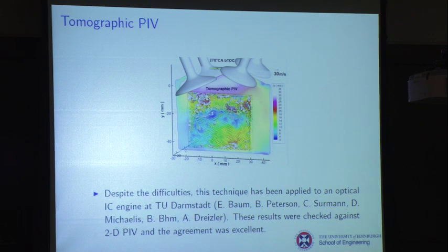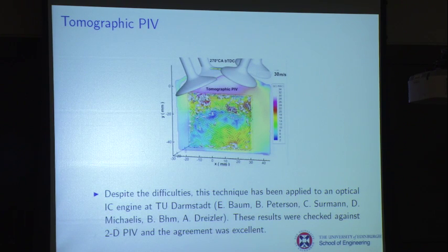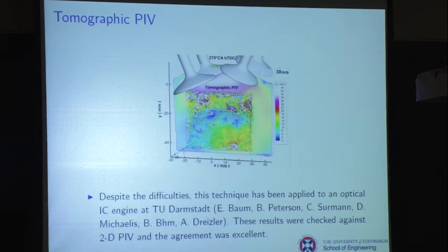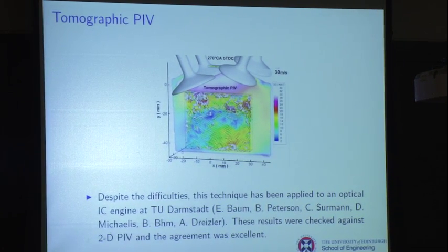So what they're trying to do is figure out how much vorticity does the spray impart in the in-cylinder gases when it shoots out like that, because in case you're not an engine person, turbulence is extremely important for propagation of a flame inside a cylinder. And especially for high efficiency engines, the pressure shoots up and then it shoots back down. Well, what you really want is to shorten the tail when it comes back down, especially the tail on the heat release rate.